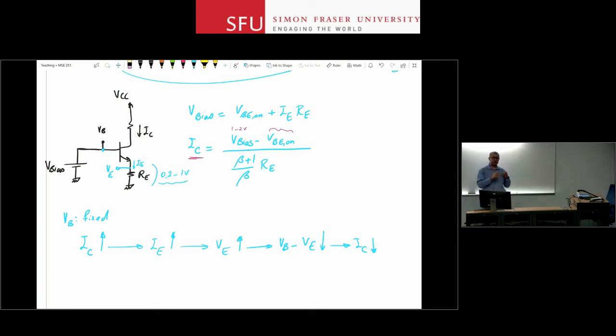And now you can go back to your amplifier stages and remember that we didn't want that RE for common emitter stage because that RE meant that we will get less gain, but sometimes it was there, right? So if you were wondering why we use an RE if it reduces our gain, well, this could be one reason, that you had to use that RE in order to get bias stability. We also saw that it has an additional benefit of increasing your input resistance, so you may be using it for that reason. But most likely you have an RE in your circuit for bias stability.